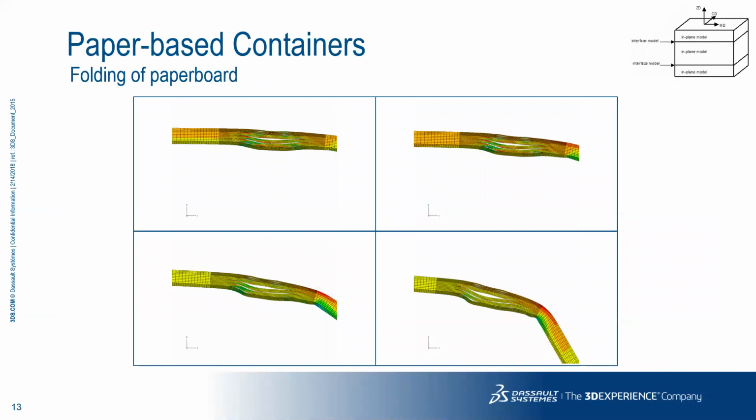But the more force you apply, the plies start to buckle, and you also have delamination happening. Progressively, the buckling is going to make your bending stiffness lesser and lesser. Once you reach a certain point, your bending stiffness is essentially constant. Your material has kind of given way. That's the broad challenge which needs to be handled.